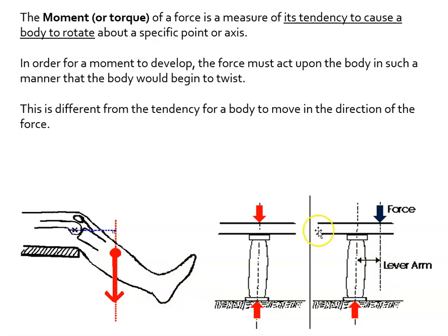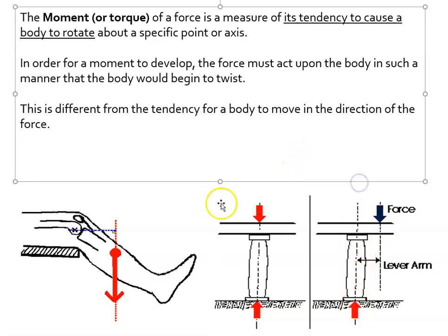That makes a difference. And here we see it in a column. Right here we see a force moving through a floor directly through the column. Here, however, the force is off to the side, and that lever arm is that direction. So now that force has to come down, and now it has to take this path over here to get to the column, and then it comes down. All right, so a detour.